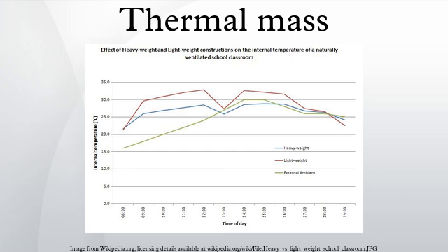For example, a 200 m2 house with 20 m2 of sun-facing glazing has 10% of glazing by total floor area. 6 m2 of that glazing will require additional thermal mass. Therefore, using the 6 to 8:1 ratio above, an additional 36 to 48 m2 of solar exposed thermal mass is required. The exact requirements vary from climate to climate.